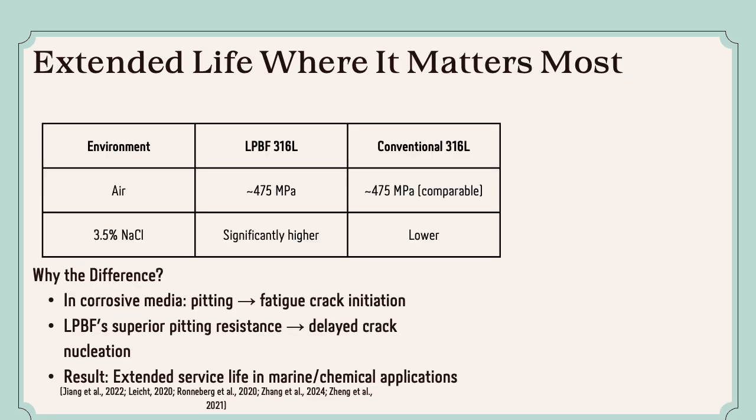This slide compares the fatigue performance of LPBF 316L and conventionally manufactured 316L. In air, both materials showed very similar fatigue strengths at approximately 475 megapascals. However, the difference became significant in corrosive environments, such as 3.5% sodium chloride solution, which simulates seawater. Under these conditions, LPBF 316L demonstrates substantially better fatigue performance.